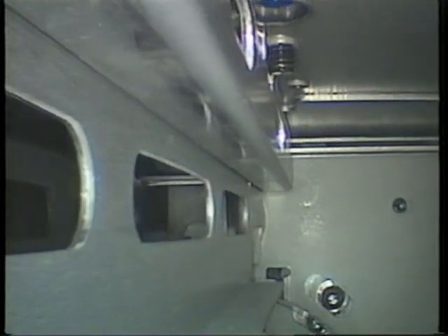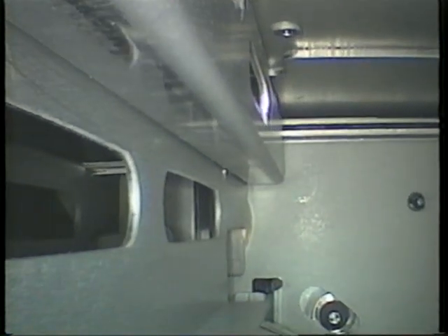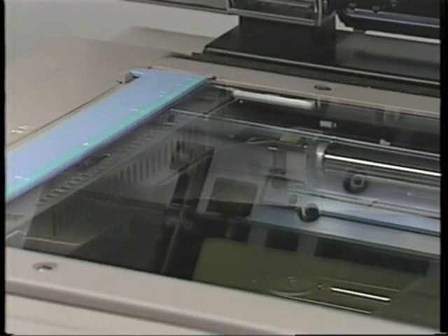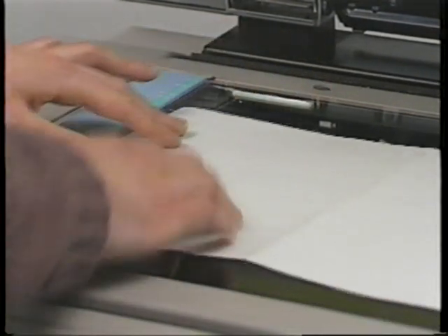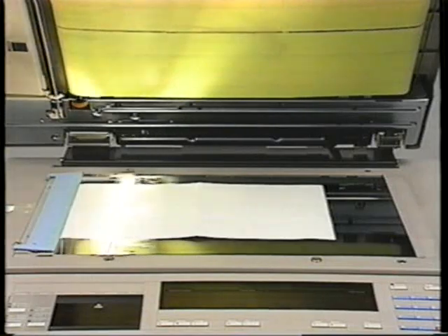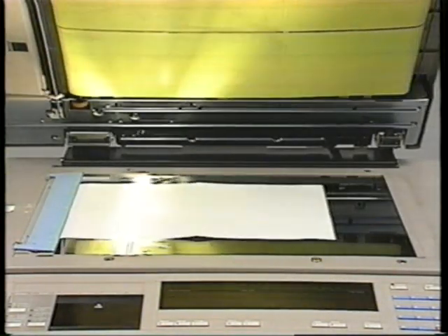Since the photoconductor is charged over its entire surface, the latent image always contains some detail that's not actually part of the information being copied. It's produced from dark areas beyond the borders of the original. This usually means marks on the document cover or the complete absence of reflection that results from making a copy with the cover open. Even the edge of the original document can produce a black line on the copy.